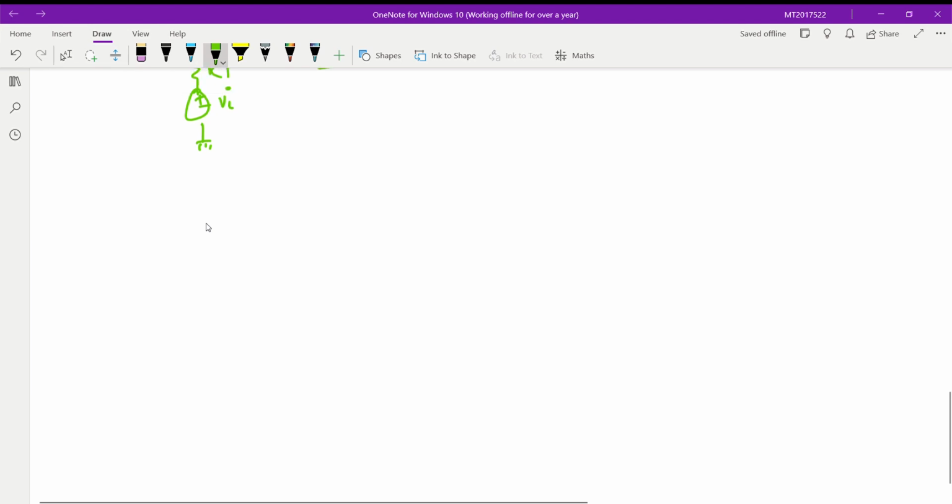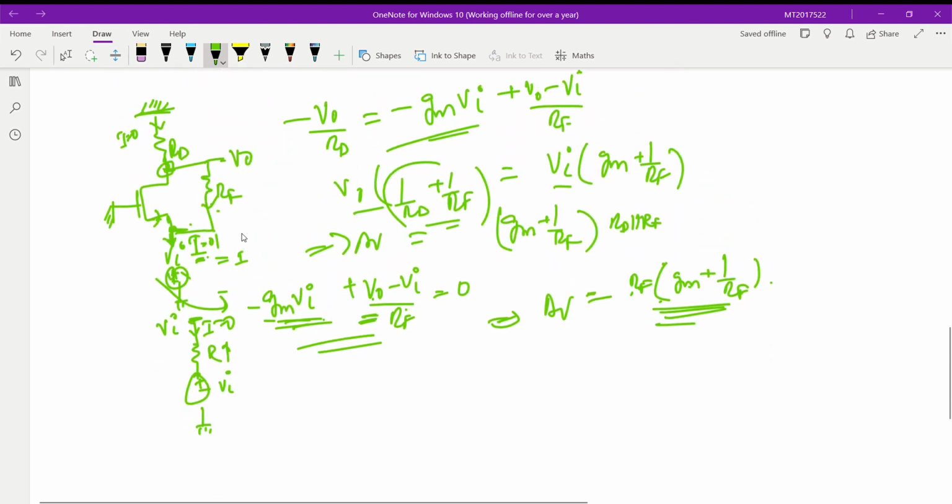One more thing. This is not a question of correct or incorrect. This is the question of what it means when you apply a node equation here with just two terms. If there are two terms, that means I going downward is zero. If I going downward is zero, that means I coming from upwards is also zero. If both are zero, then you simply have a circuit like this, and that is what you are getting here.